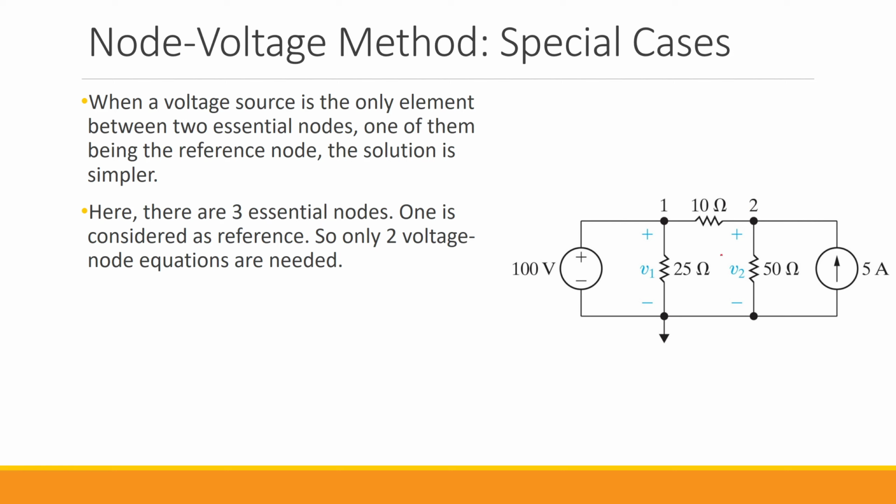So once again, we find the nodes in the circuit. Here we have this as a node, this one as another node, and finally we have this node too. So we have in total three nodes in this circuit. Out of these three nodes, which ones are essential nodes? As you can see, we don't have any nodes that are only the point of contact of two elements, right?